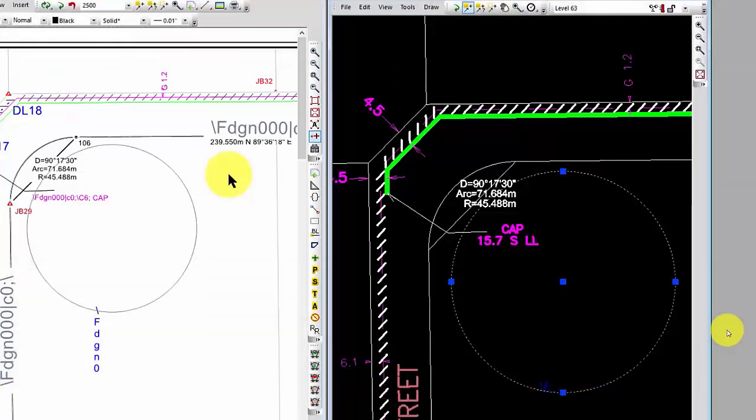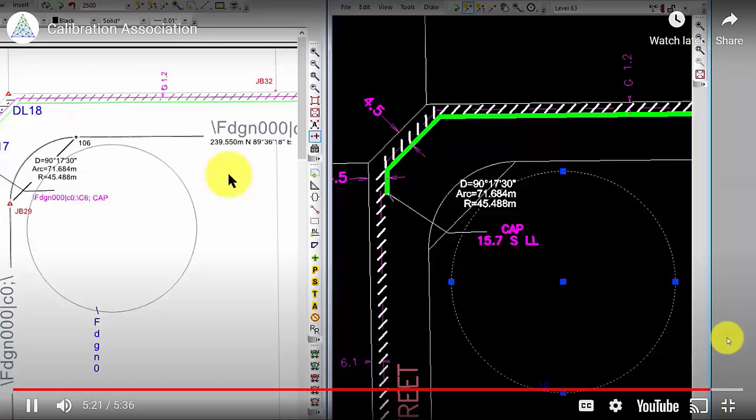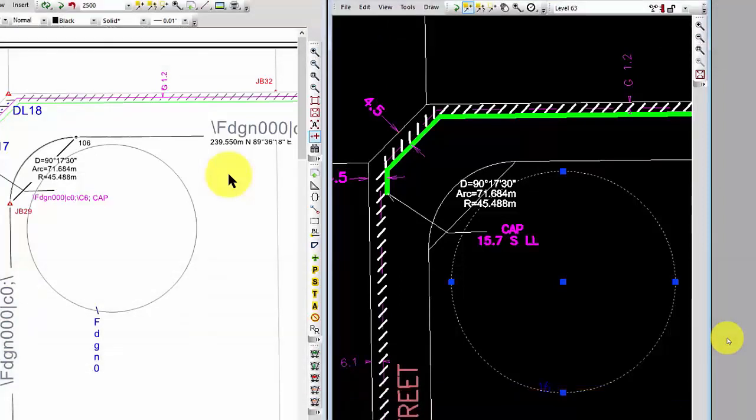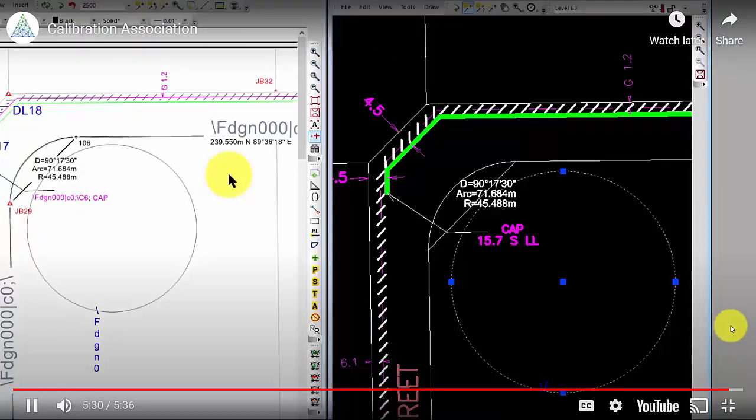I mean, how many times do I get a CAD file that's in inches, not feet, or based on local site when I'm in state plane? Just all kinds of reasons that they're not on the same grid. And this says, hey, that's not a problem. I can work back and forth between the two of them with a calibration.